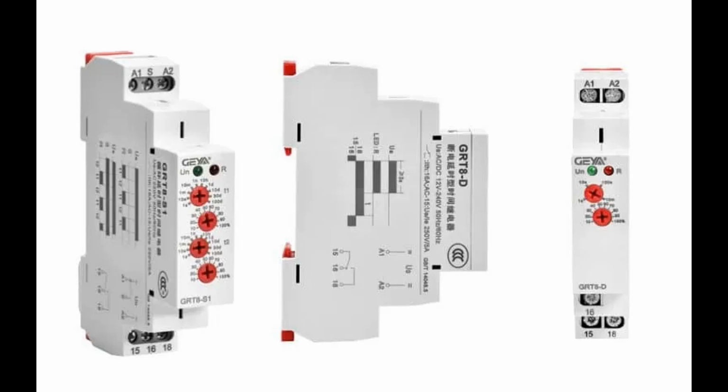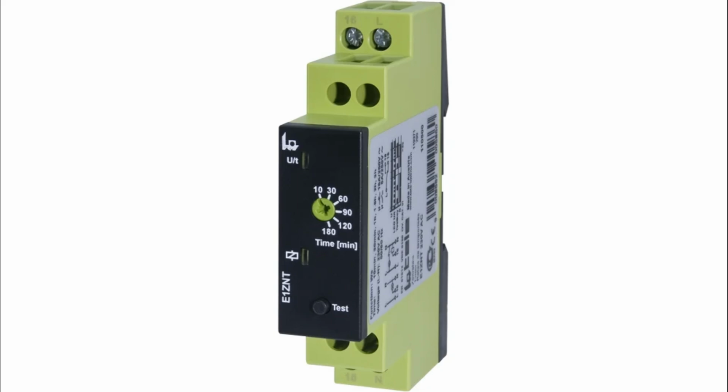Time delay relays may incorporate various protective features to enhance the safety, reliability, and longevity of the relay itself and the connected electrical circuit. Here are some common protective features found in time delay relays. Overload protection. Overload protection mechanisms safeguard the relay and connected equipment from damage due to excessive current flow beyond the relay's rated capacity. Overload protection may include current limiting circuitry, thermal protection, or electronic overload detection to trip the relay and interrupt the circuit if an overload condition is detected.